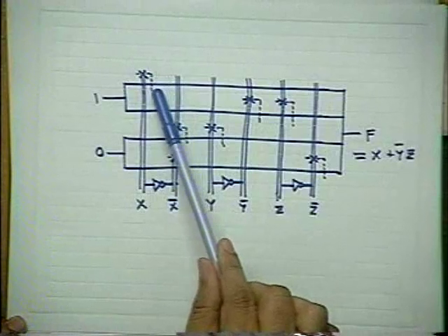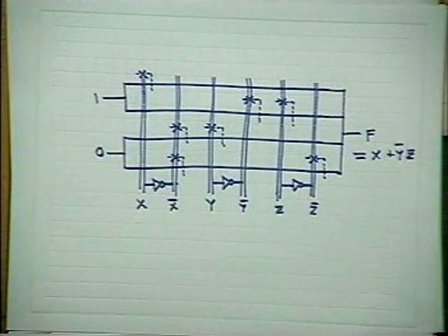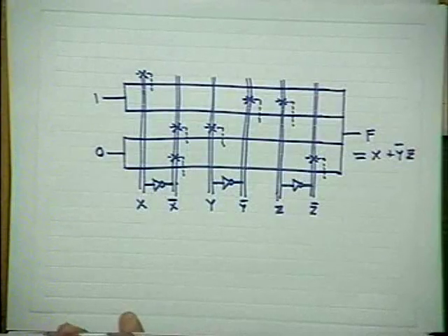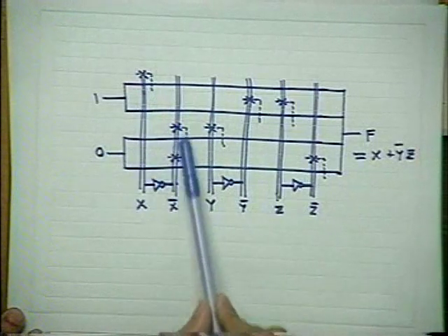Actually the poly level is below this. Please remember, metal comes at the end. In actual VLSI realization, metal deposition and patterning comes at the end. Before that, poly comes. So what do I have to do? Already I have MOSFETs everywhere. At all intersection points, underneath there is a MOSFET. But these MOSFETs are all covered by oxide. They are not accessible. There are polylines also, so at each intersection there is a polyline. The polylines are already available.